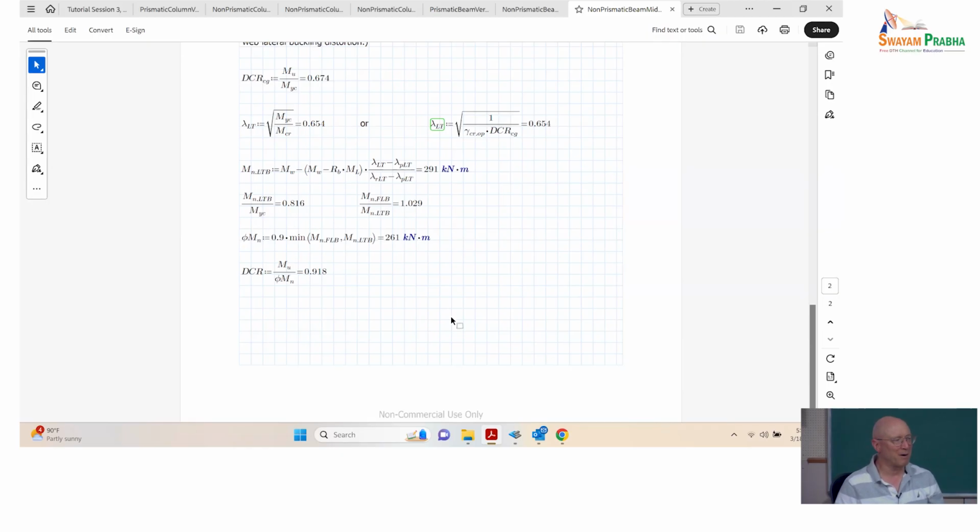That's where we do our calculation. That usually does pretty well for beams, because of some of the silliness of the way Rb works with the equations. You can sometimes get other cross sections that actually give you a little bit larger demand to capacity ratio for the member checks, but it's not significantly different.